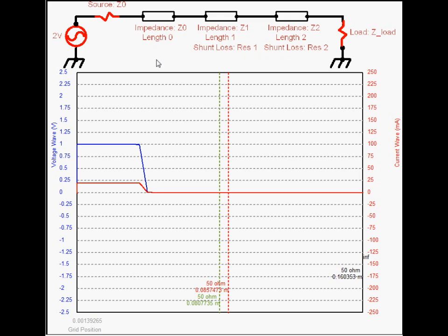For an impedance, we still have that same sort of relationship. We have a voltage, 1 volt, equal to the current, here 20 milliamps, times the impedance, which we've set to 50 ohms. So that relationship holds for the AC case, for the high frequency case. It just doesn't hold necessarily for the steady state case. So that's your fundamental difference for the impedance.